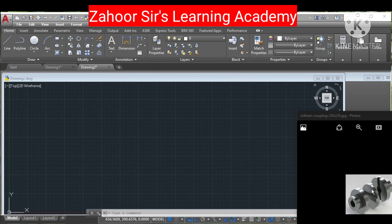So it comprises three parts. The middle one is the disc. This disc has two tongues, one horizontal tongue and another vertical tongue. These tongues are fitted in these grooves. This flange has a vertical groove, and the vertical tongue goes into the vertical groove, and this horizontal tongue goes into the horizontal groove of the other flange.